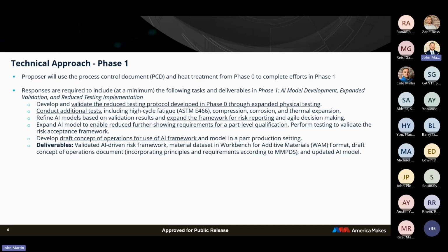So for the selected alloy 17-4 PH, several of the proposed tests, such as tensile testing, already have existing reference data. Could we select tests that already have established references so that results can be compared later? For example, MMPDS includes critical tensile data for this alloy produced by AM.